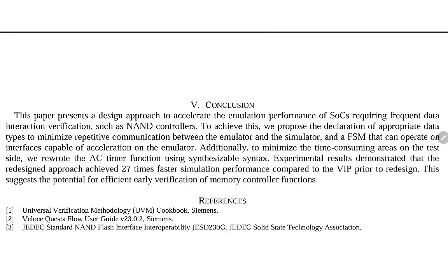Chapter 5, Conclusion. This paper presents a design approach to accelerate the simulation performance of SoCs requiring frequent data interaction verification, such as a NAND controller. To achieve this, we propose a declaration of the appropriate data type to minimize repetitive communication between the emulator and simulator. An FSM can operate on interfaces capable of acceleration on the emulator.